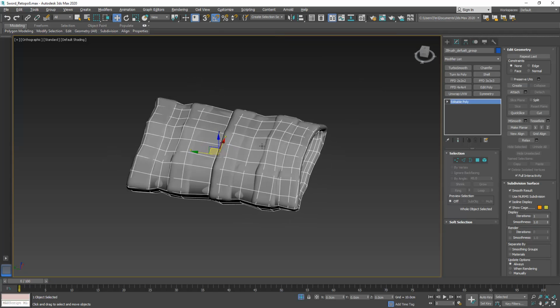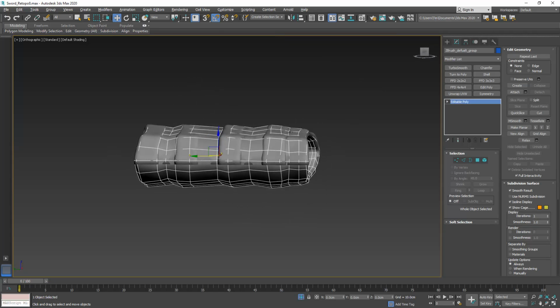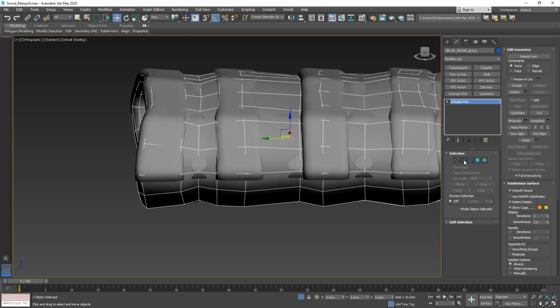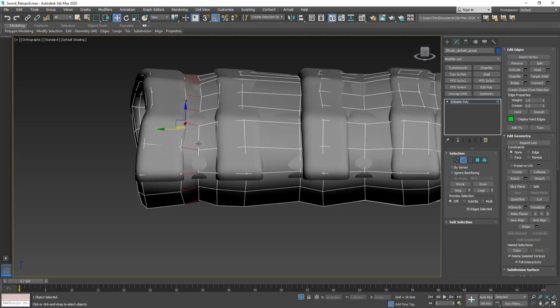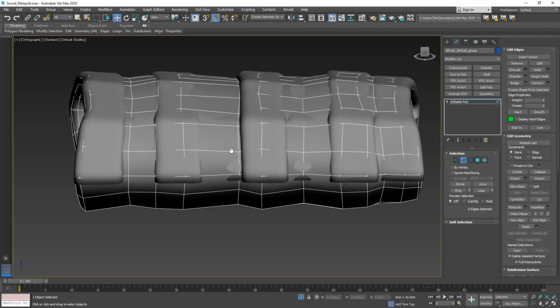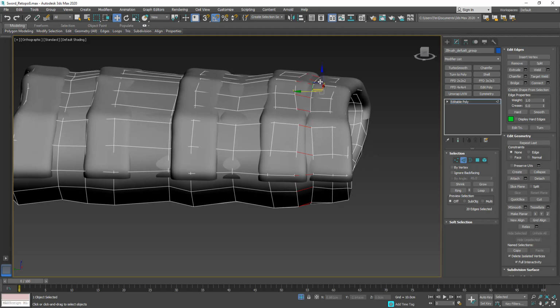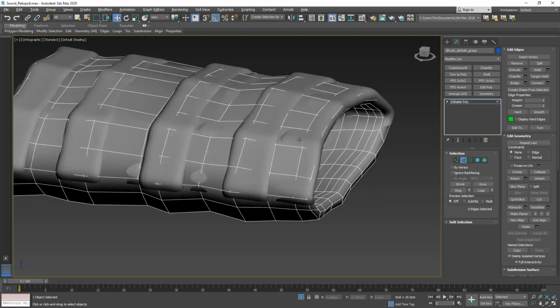I'm gonna take both of them here into our isolation view. Makes it easier to see what we're working on. Gonna have another ring selection here and collapse it. And here as well. Let me undo that to see if that works. Yeah, let's collapse this.